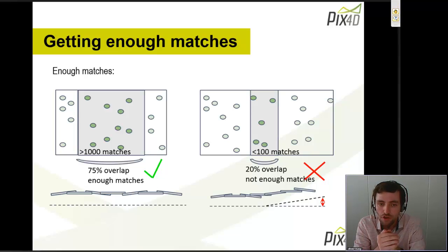In such a model, you would only need, and this is what happened in traditional photogrammetry, a few tie points per image. Let's say a few dozen tie points per image, which is enough if you are in a traditional photogrammetry context, which means a good camera, good GPS, good IMU, good sensor, and very high altitude. This is generally enough. And this is a big difference with the new modern photogrammetry that Pix4D Mapper is doing.